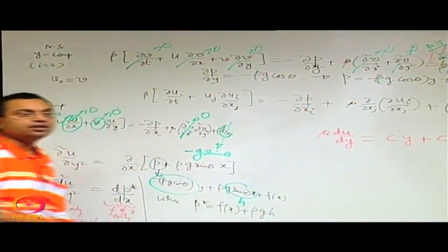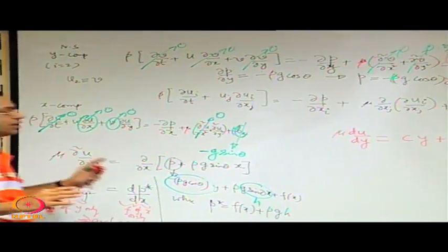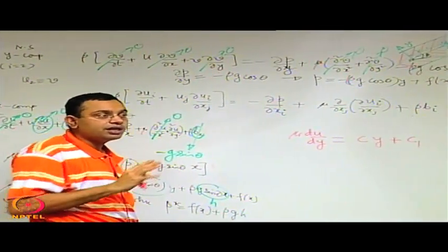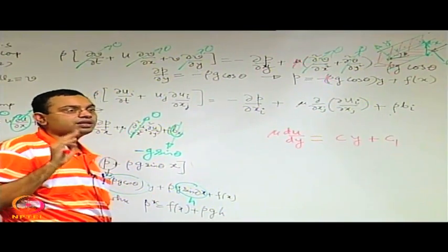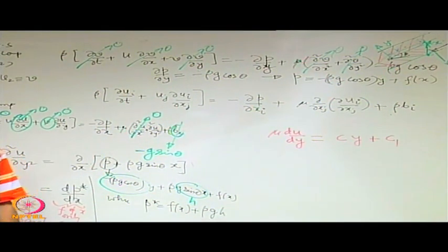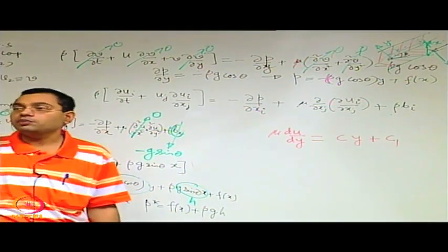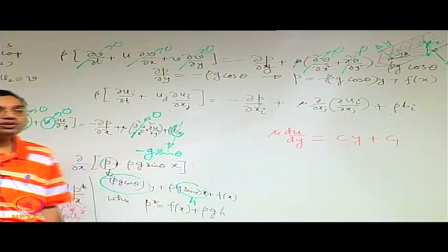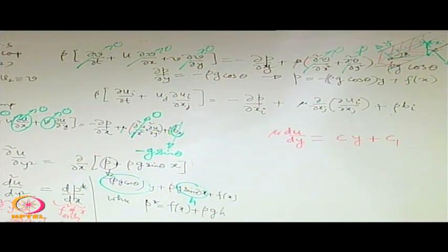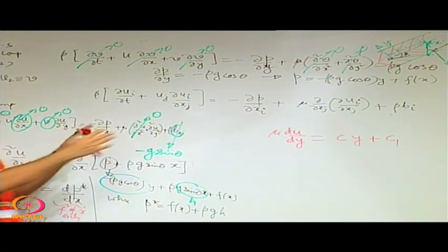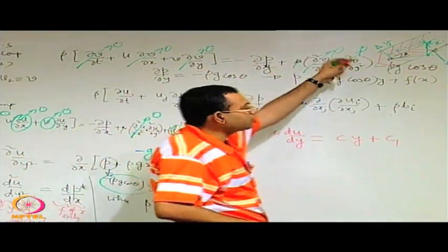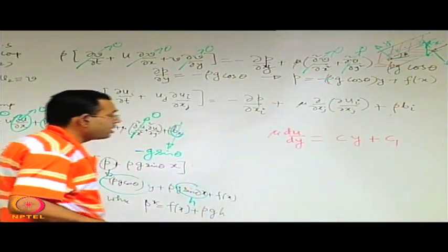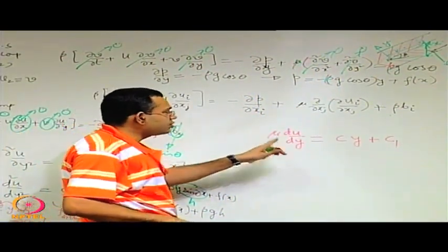So it is something which one should always utilize if you find symmetry. Remember, symmetry should be in terms of three important things: symmetry in geometry, symmetry in boundary condition and symmetry in physics. So we have to make sure that all these three things are maintained, and here all those things are maintained in the top half and the bottom half.